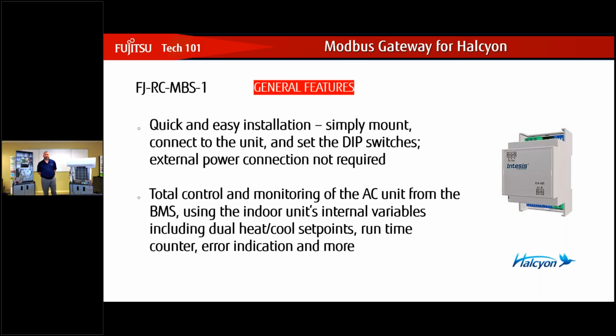All right, getting over to the building management side, we have our Modbus building management system. This is a quick and easy installation, just like the other one, another very small part, roughly about this big, maybe 3 inches at most. Gives total control to the building management system, so you can control it through the Modbus building management system. You can adjust anything from dual heat and cooling set points, runtime counter, error indication, all that. Those displays will be sent to the building management system.